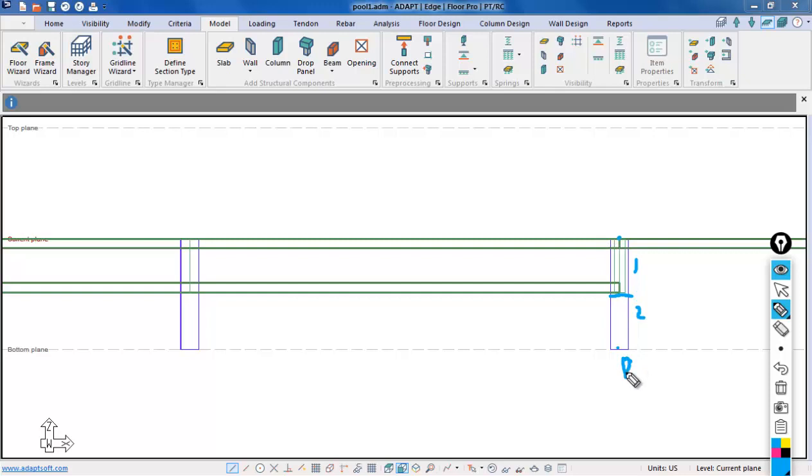This would be the bottom reference plane, which is called bottom plane, and the top reference plane of the column is shown here, top. So if the node of the column, and I'll put the node in pink, is below the reference node or the physical node of the beam, in this case it's obviously below this, this is acceptable.